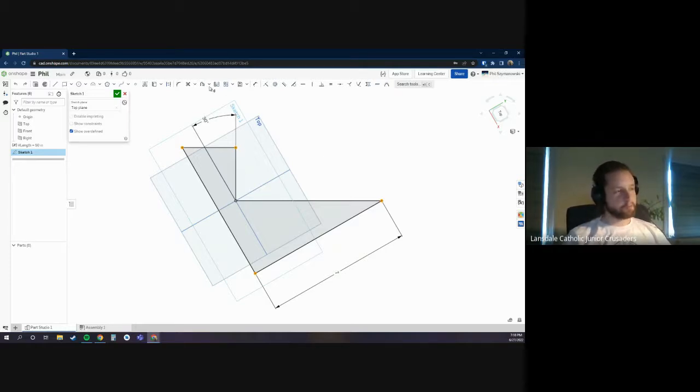And then while you're selecting things, to deselect something, you can click off of the object, like in the white space, or I believe it's the space bar in Onshape that will clear your selection. I think it'll actually clear what feature you're using. No, it doesn't clear whichever constraint you're using, but the escape key will clear your selection and whatever you're using.